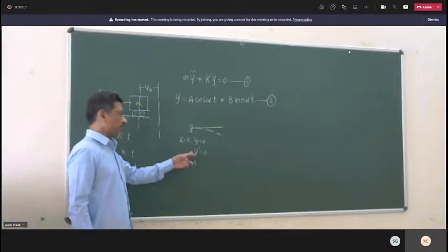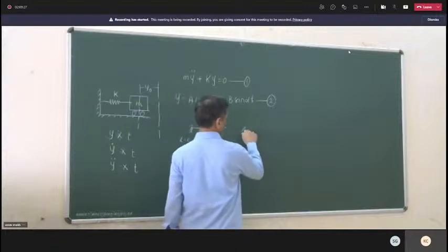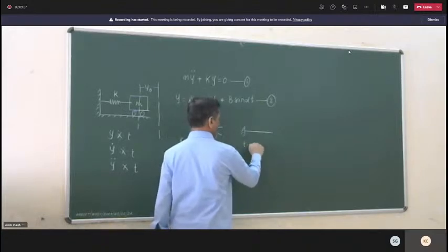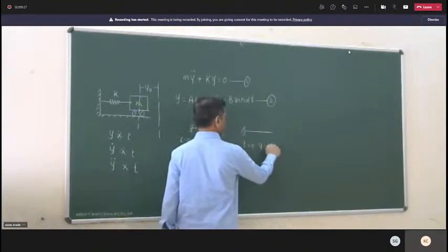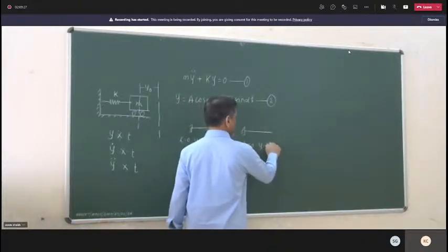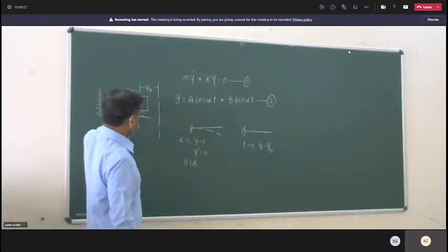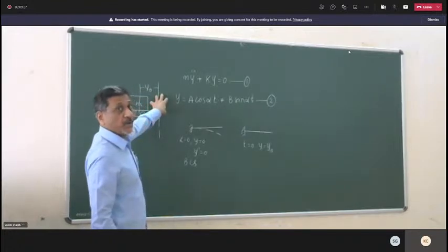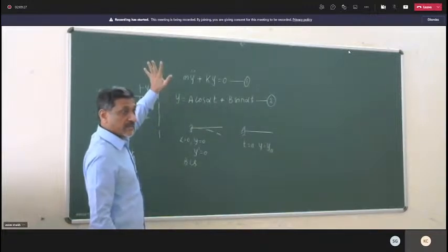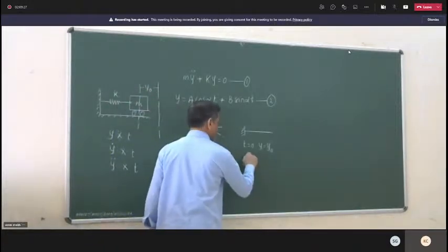They are x dependent, dependent on space. Same cantilever beam. It is vibrating at t is equal to 0. Its displacement is 0, y is 0. Or if you are giving some initial displacement, you can say y is y0. Like in this problem. At t is equal to 0, you have pulled this mass, still you have held it in position, still it is at rest at y0. And now you are releasing it. So at t is equal to 0, y is y0 is the initial condition.